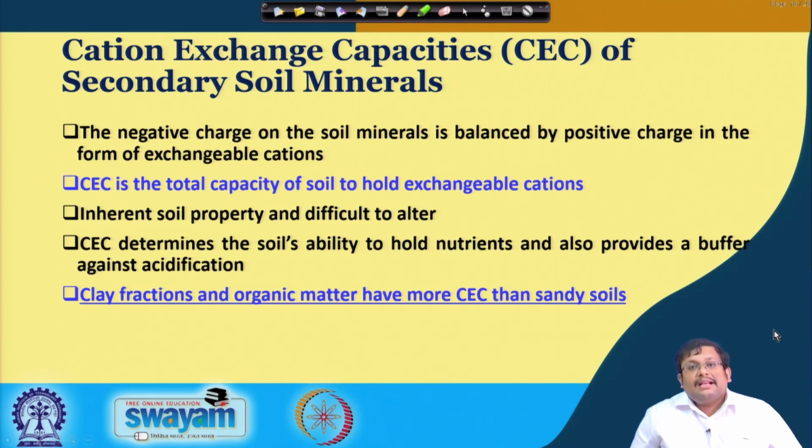Another important thing is the cation exchange capacity of secondary soil minerals. The negative charge on the soil minerals is balanced by positive charge in the form of exchangeable cations, and cation exchange capacity is the total capacity of the soil to hold exchangeable cations. It is an inherent soil property and difficult to alter, and CEC determines the soil's ability to hold nutrients and also provides a buffer against acidification.